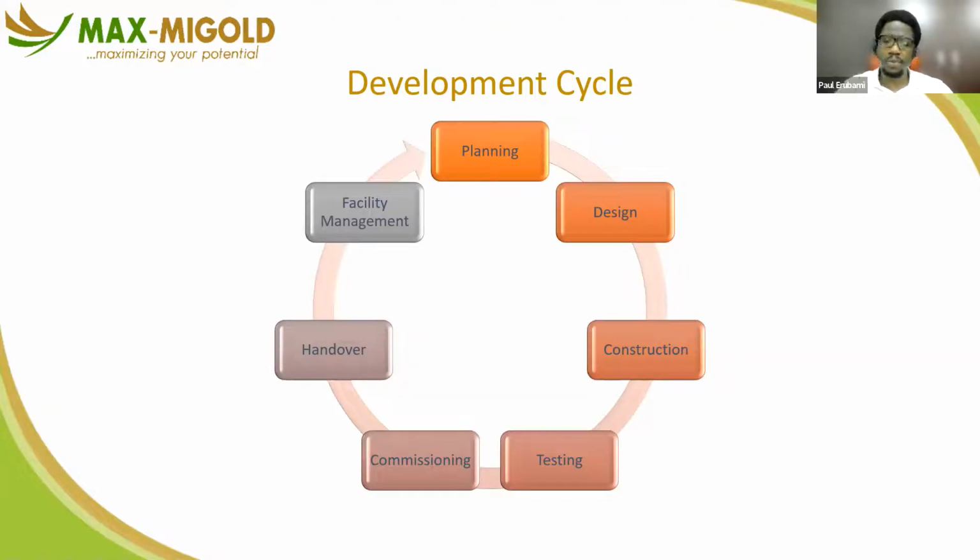Two other things that happen within the construction and after the construction are testing and commissioning. Testing is a process for checking at the delivery points whether there are errors or whether it is functional, right? So it's a test for functionality. It's a check for whether the item will work or not. It's different from commissioning. Commissioning is a test for adequacy, checking whether the item that is working will meet the requirements of the users. That's commissioning. So it's a different process altogether.